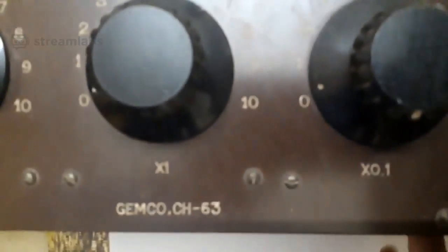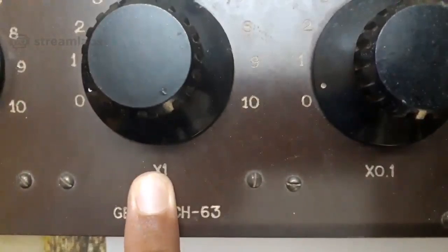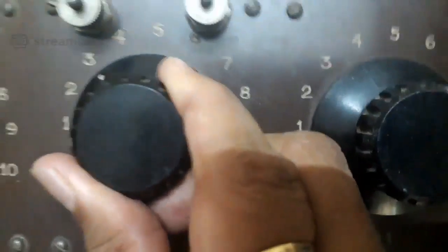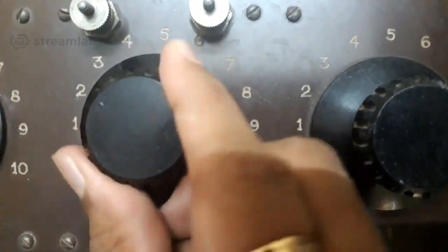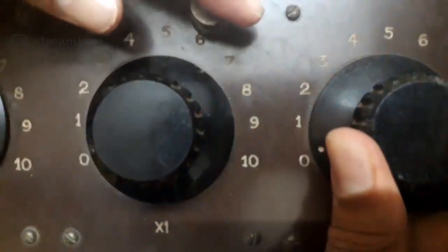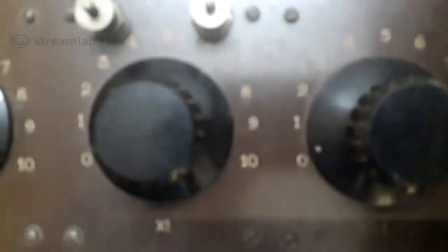See, now I think you are able to see it. It is a multiplication of 0.1 ohm. Yeah, this is a multiplication of 1 ohm. And can you see there is a knob and it has an indicator. By turning the knob, you can keep it at 1, 2, 3, just like a regulator in a fan. Suppose I keep all the knobs at 0. These are the two terminals for the connection, connected across the right gap. All the knobs at 0.